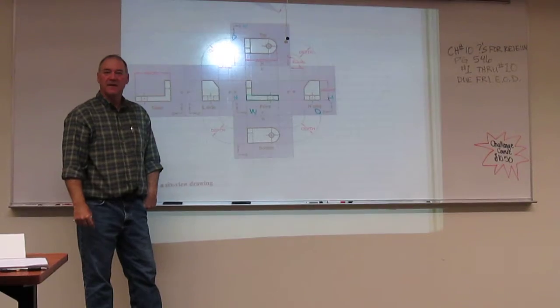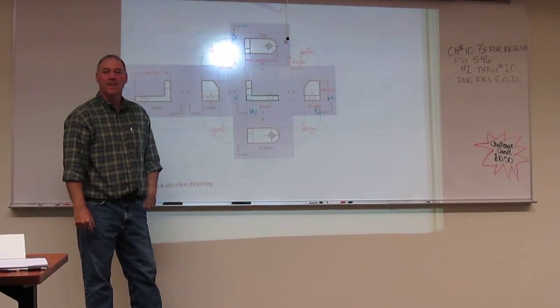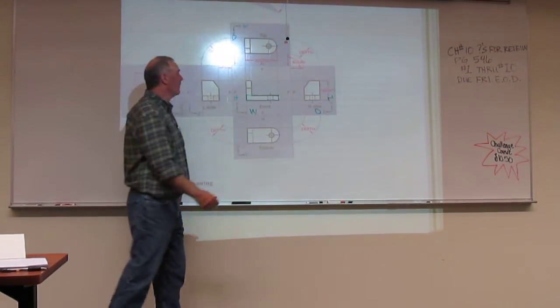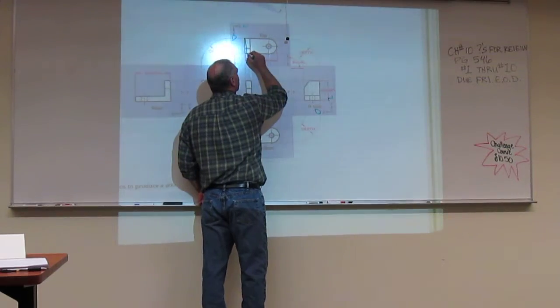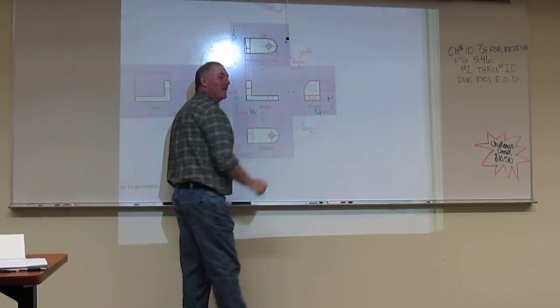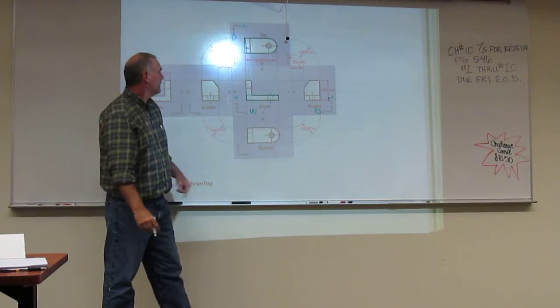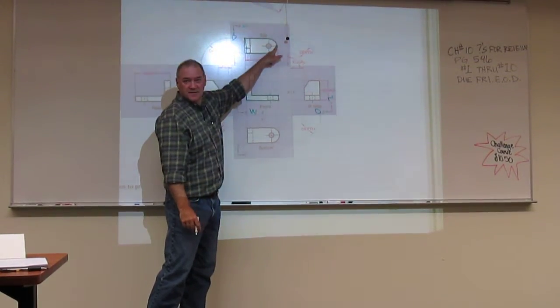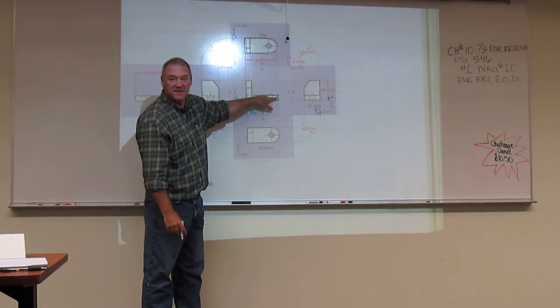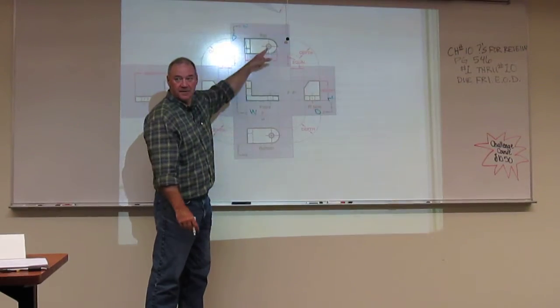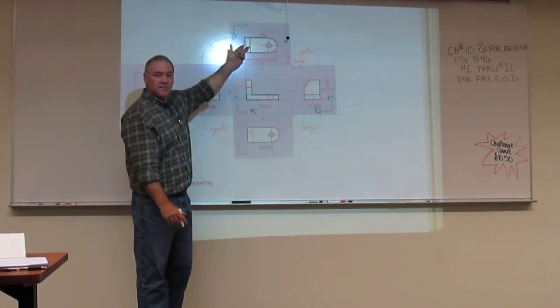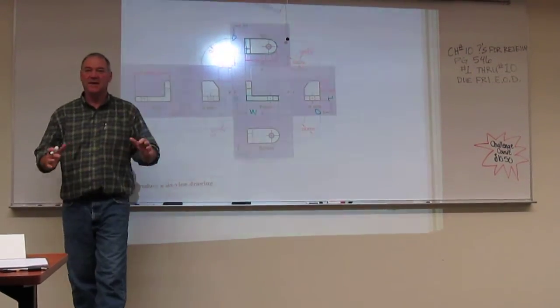What's missing off of that for somebody to build that? The depth. Okay. Where are they going to get that? Looks to me like they get it from right here. Okay. There's the depth of that same rectangle. We also find out that this end is a positive cylinder, and we're seeing a limiting element right here based on that. That's completely described. You've got height, width, depth of this rectangle.